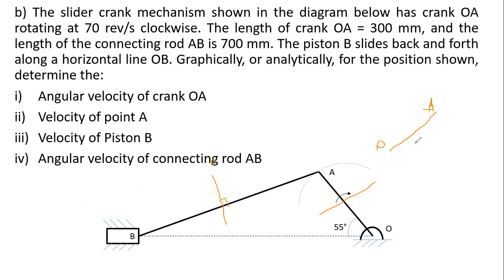Right, OA. Then from there, the next one that you bring up is this one here, representing AB. Since we are moving clockwise, it means it's moving in that direction. With the help of your set squares and instruments, you transfer this there. You just draw it randomly like that. And lastly, you bring OB, the movement of the slider, because this is moving in a straight line. It will be transferred there blindly, because we don't know where they will meet. So they meet at point B.